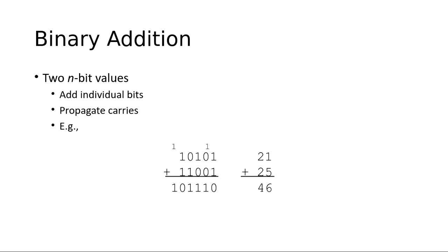Now look at this. 1 plus 1 is 0, and you see there is a carry going to the next stage. So 1 plus 0 plus 0 will become 1. Similarly, the simple addition will go on, and in this stage as well, 1 plus 1 becomes 0, and carry going on to the next stage, and you will get 1 here. If you convert this into decimal, you will get this number. You can try it, and you will get the same thing.